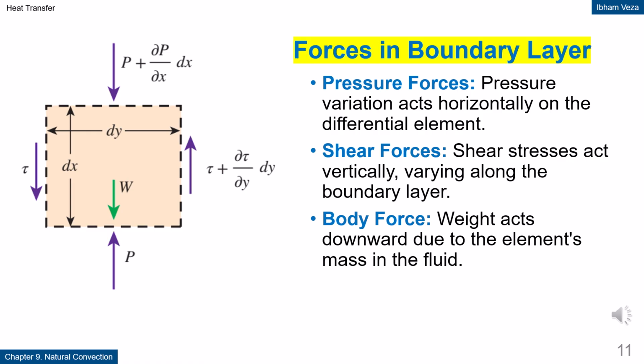Forces in boundary layer. A fluid element inside the boundary layer experiences several types of forces simultaneously. Pressure forces act horizontally due to pressure gradients. Shear forces act because of fluid viscosity and vary in the vertical direction. In addition, the weight acts downward as a body force. The balance of all these forces determines the acceleration and flow pattern of the fluid.